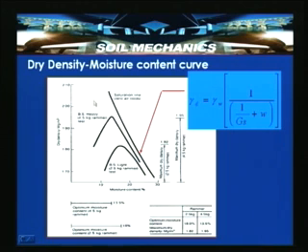So the energy difference between these two is around 4.5 times. This curve is obtained by giving an energy of 4.5 times the energy of this particular curve. So for the modified Proctor compaction test, you will see that the curve shifts to the left hand side and shifts vertically upwards. That indicates that the soil particles are coming closer by expelling the air quickly. So this additional energy is enabling the air to be expelled quickly from the soil solids, and that makes the difference between these two.